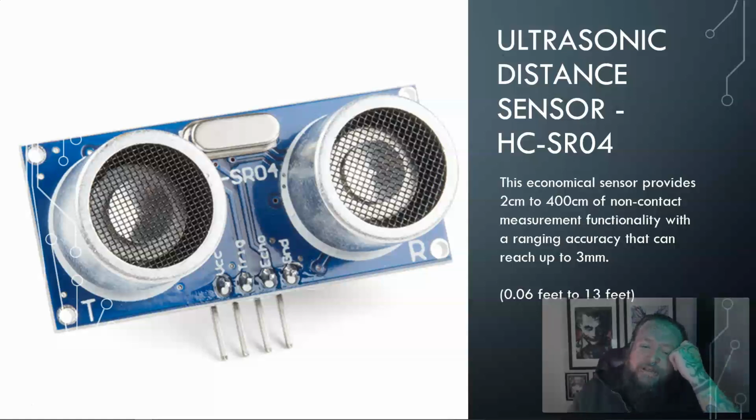All of that needs to be taken into account, but hey, it's a good starting sensor. If you know these things, you can modify your code to not expect exact measurements, but close within a level of tolerance, and then combine that with where you physically place the sensor on the robot and what will actually happen.